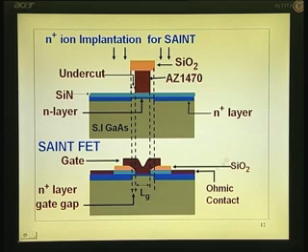See, if you do not have this n plus layer, you get the effect of the thin layer of the channel, which is doped rather lightly, the doping concentration in the channel being decided by other factors like threshold voltage, etc. So, you have the series resistance. The moment series resistance is there, the transconductance is lower, gm0 by 1 plus gm0 into Rs. So, that pulls it down.